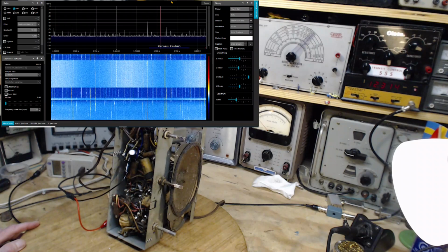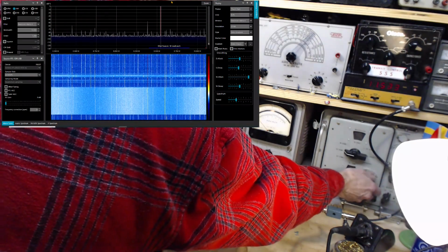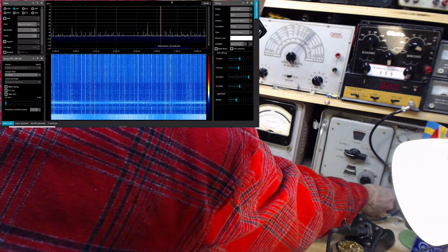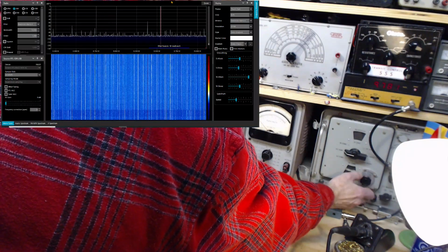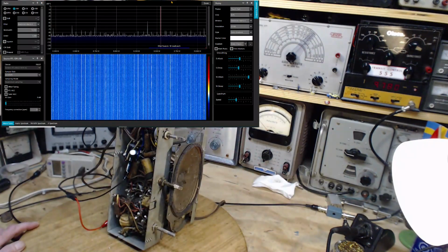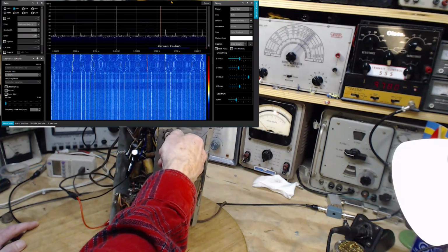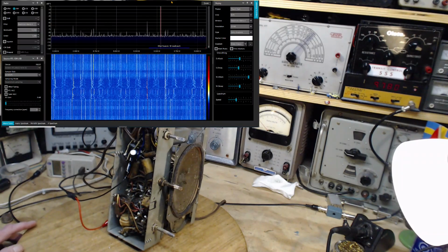Okay, and 9. Okay, so again, the signal strength here is the strongest signal you'd ever get from an antenna. That kind of level. And the volume is up full. This thing should be screaming out, but it's not. So now we know the radio is tuned to 9780.